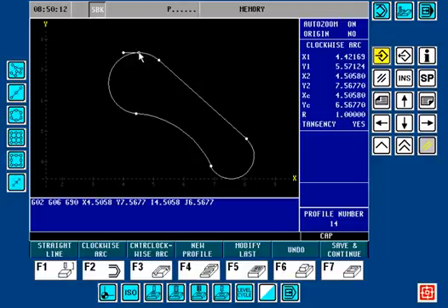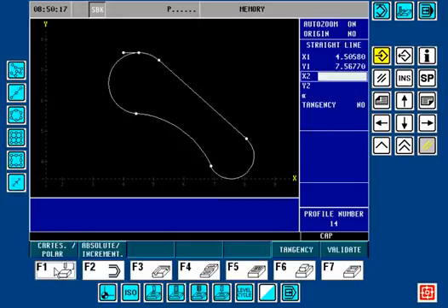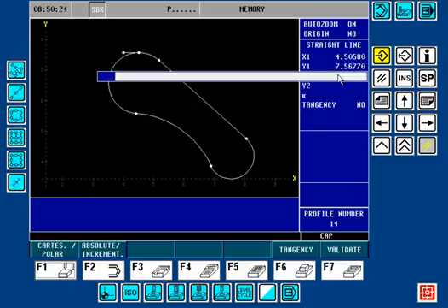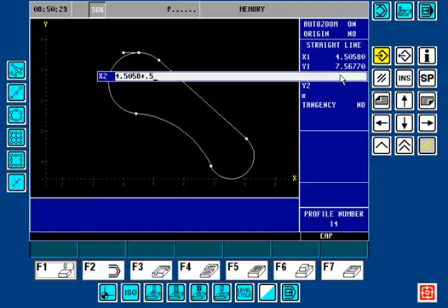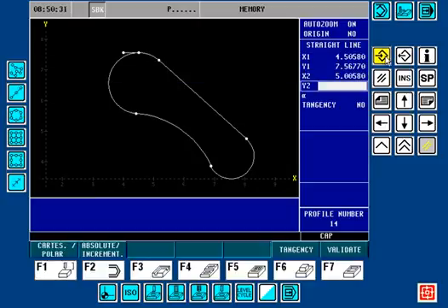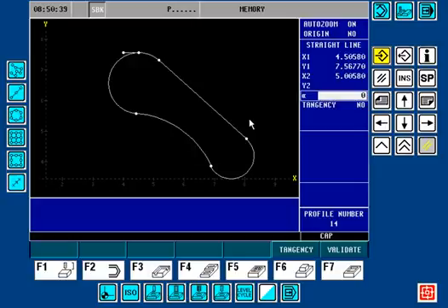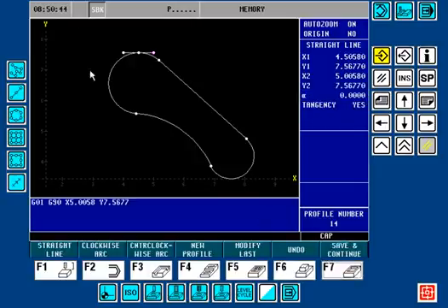All that remains is we need to have a lead-off exit. For that we'll do another straight line. And we're going to have x go to 4.5058. And I'm going to press the plus on my keyboard and add 0.5 and enter. The y will remain the same, but I'm just going to say that the angle is 0. Again, we're going to be traveling in a 0 angle, and again that will be tangent to the previous arc, and validate it. This project is now complete.